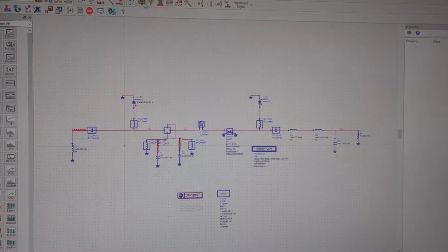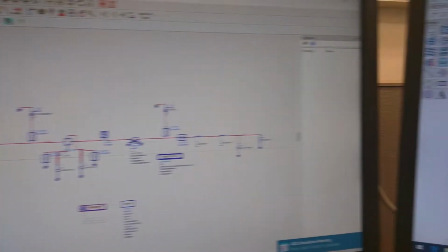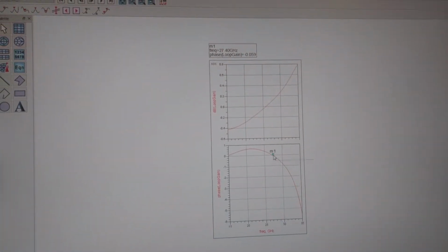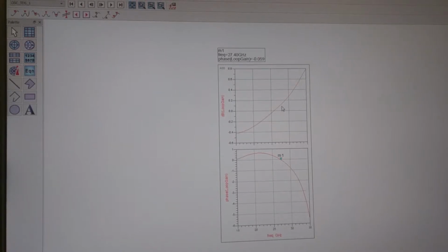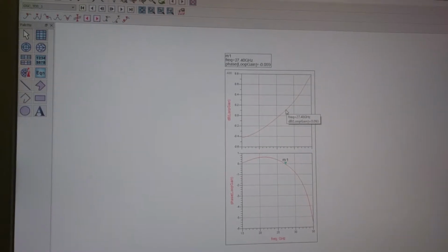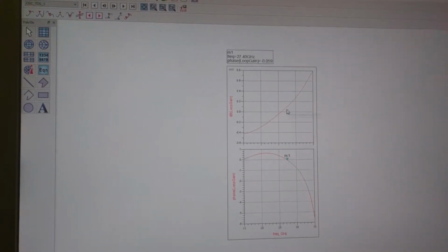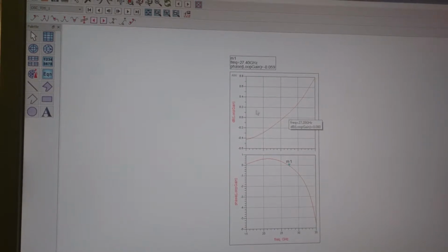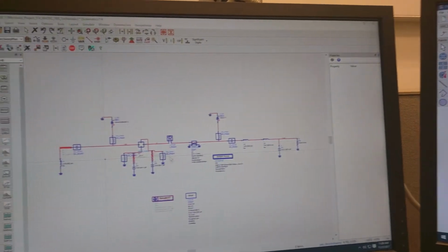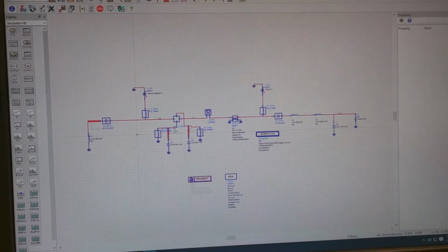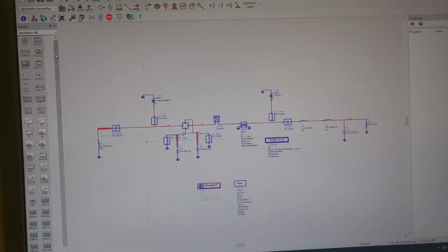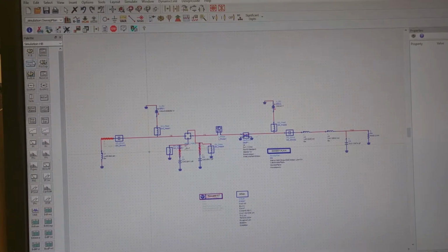Now if I rerun this simulation, these are the results, and here you see that the phase 0 crossing is happening here, and we have a gain which is greater than 0, but the frequency has now shifted to about 26-something gigahertz. So this suggests that this is going to oscillate. The next step would be to run the harmonic balance simulation and figure out exactly at what frequency it is oscillating.